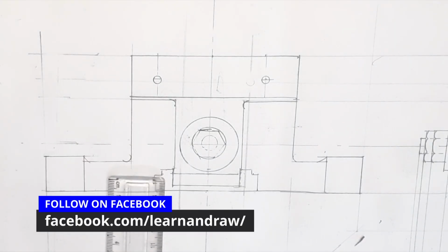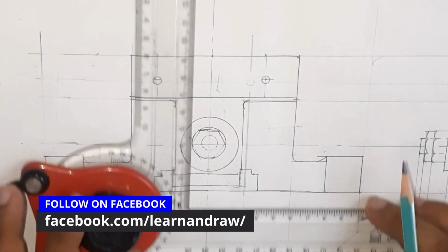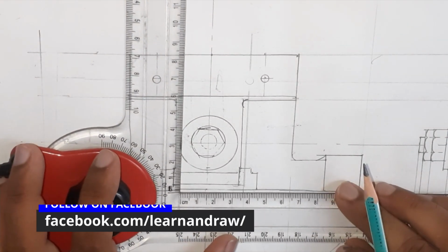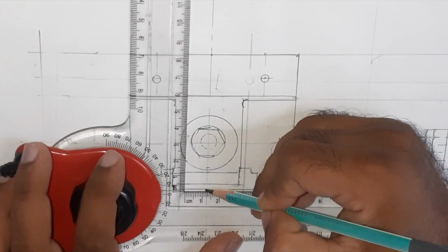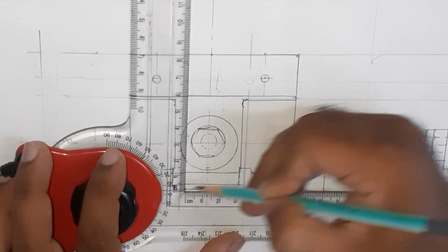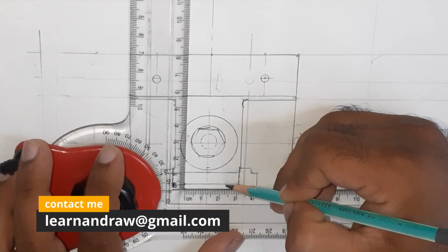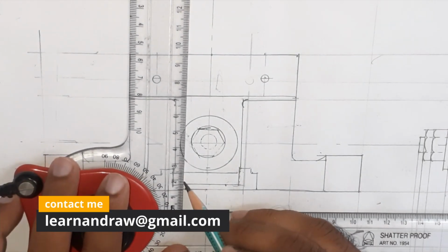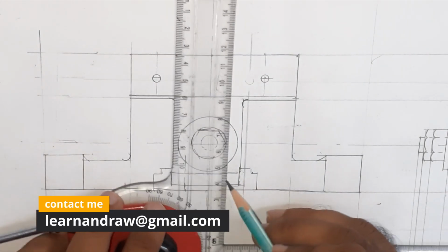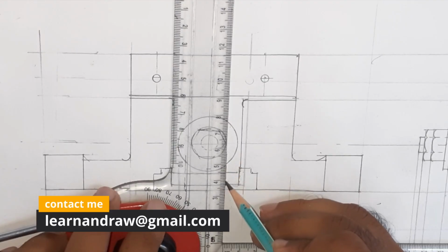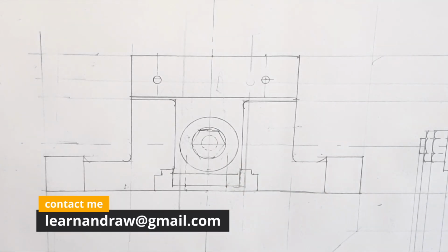Okay, so the last part is we have to draw the screws here. The screws are 24 mm apart, okay. So that is we have to mark here 12 mm and here 12 mm, okay. So here we will draw the axis line. So here also we will draw the axis line. So over these two axis lines we have to draw the screw.